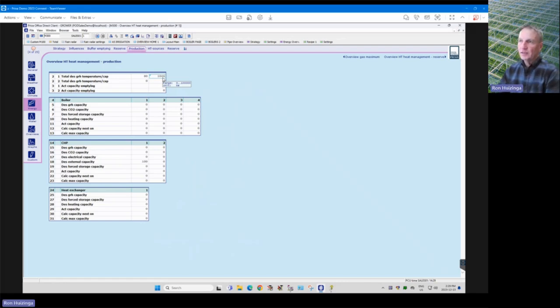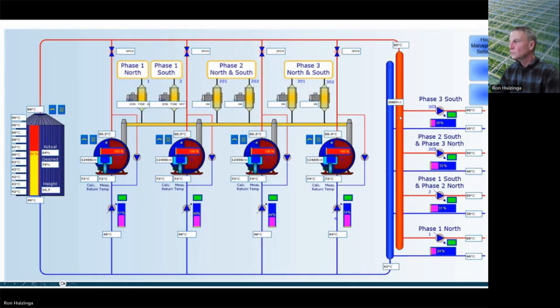You can look at this number here, the kilowatt demand from the greenhouse, and you can graph that number over 24 hours, and then divide it by the hectares of your greenhouse, and calculate it out. So for this one, right now the greenhouse demand is 26,000 kilowatts, and I know this greenhouse where I took the screen capture from is around 30 hectares. So at that point you have around 100 kilowatts a hectare for that example.